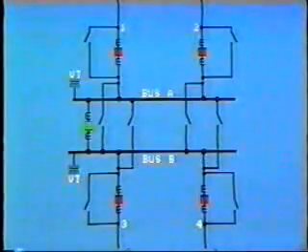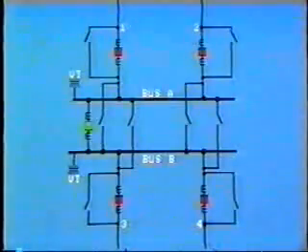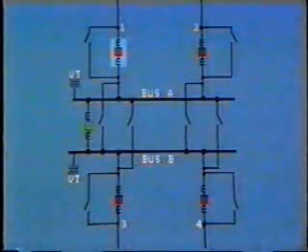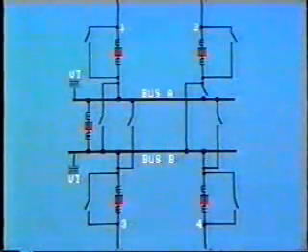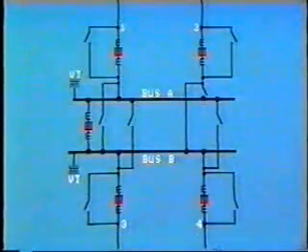In order to provide more flexibility, this configuration allows us to remove a breaker from service without interruption. For example, let's say we wish to remove breaker number 1 on circuit 1. All of the remaining circuits would now be connected to the B bus. The bus tie breaker would now connect bus B to bus A, which now becomes the transfer bus.